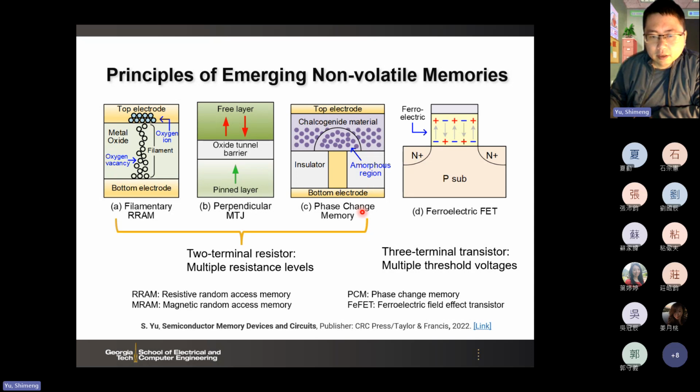then we have a high resistance state. So here, today's topic is on the ferroelectric, and one of the ferroelectric device structures is the ferroelectric field effect transistor, FeFET. So here we replace the gate stack of the normal MOSFET with the ferroelectric material, where we can have a spontaneous dipole built into the gate stack.